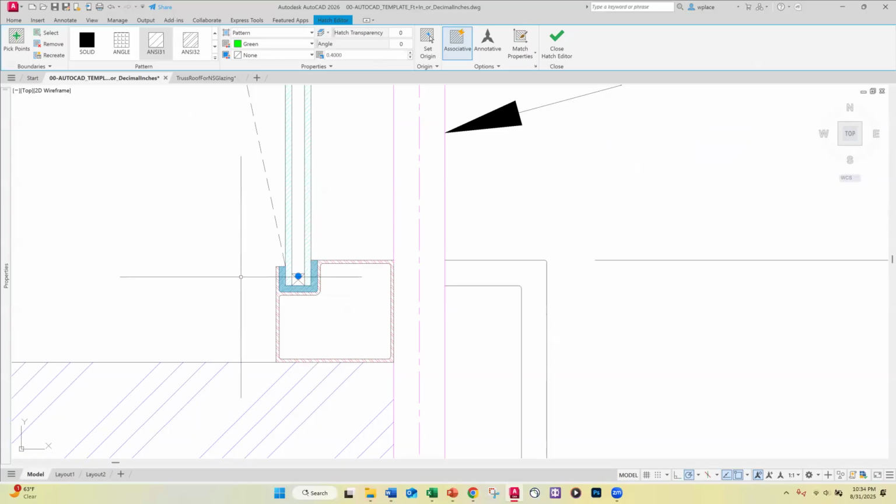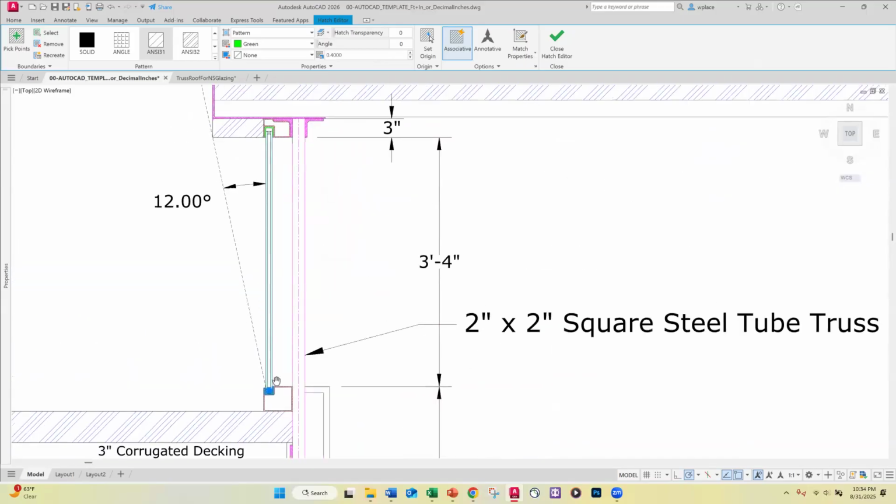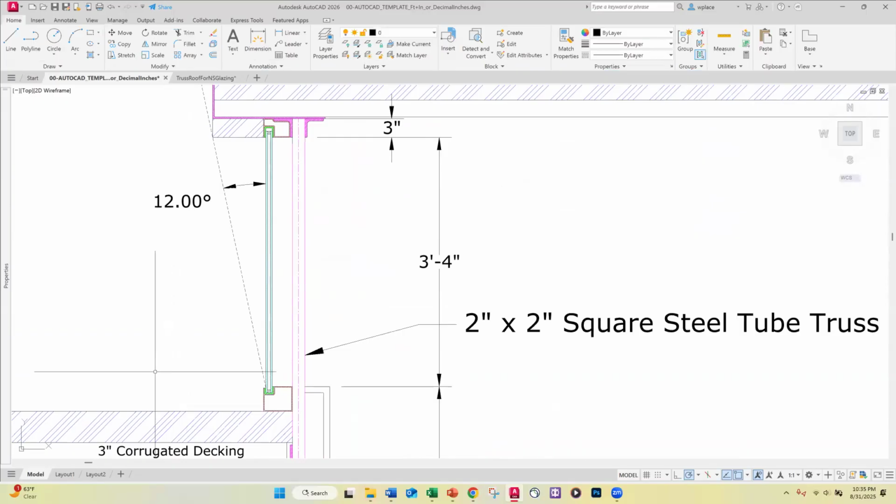So you need about a 3/4 inch overlap between the glass and whatever's grabbing the glass. And of course, since we want it deeper on the inside, it's more than a 3/4 inch interface. Okay, so I want you to ponder all that.